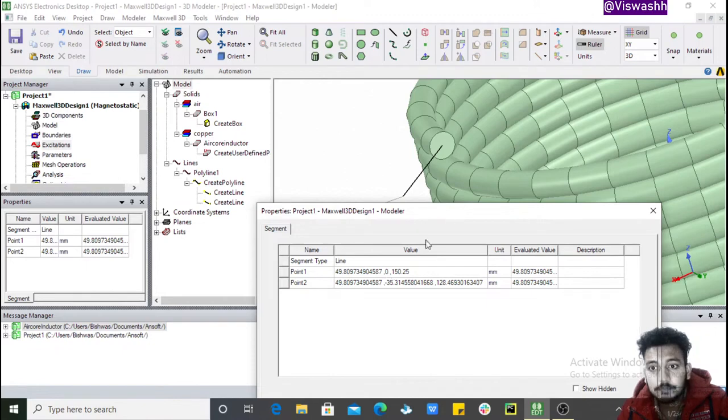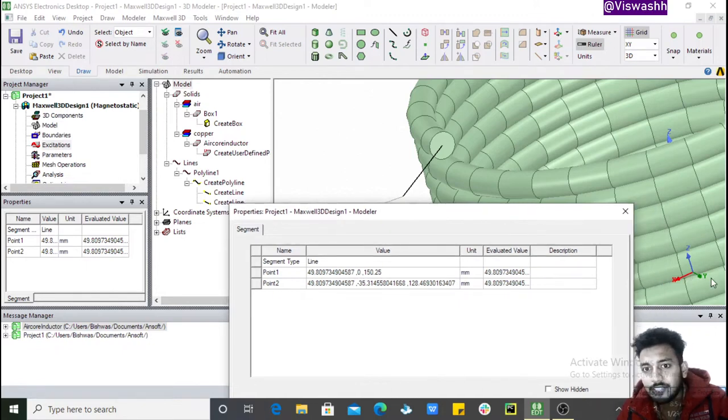Now the Y value is 0 here, and you can see the Y value is in this direction. That means it will come forward in this direction, and that we do not want for this point at least, but we particularly want it for this point, because it must change in the Y value for this point but have no change in Y value for this point, because it must be attached to the solid. So for this point, Y value 0 is very valid, and it must be like that.